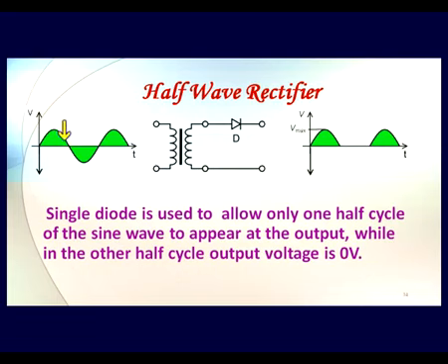We are going to have a rectifier where our AC input is varying around a 0 value. If we attach a diode like this, then whenever there is positive at the anode with respect to cathode, that particular voltage will be passed through this diode. But in the negative half cycle, if you see what happens, we have negative here, and through the circuit completion we have positive here. It is a reverse bias of the diode, and so this is a switch which is switched off.